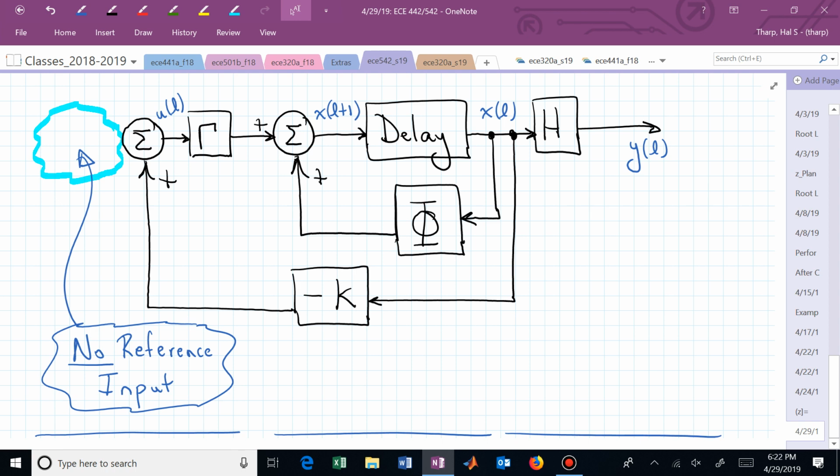Yes, our output is simply a linear combination, and so now, instead of independently measuring the state variables, with output feedback, we're stuck with some linear combination. We have to feed back x1 plus 6 x sub 2 in that combination, weight it, and that's why we're forced not to be able to manipulate the closed loop poles arbitrarily in the z-plane.